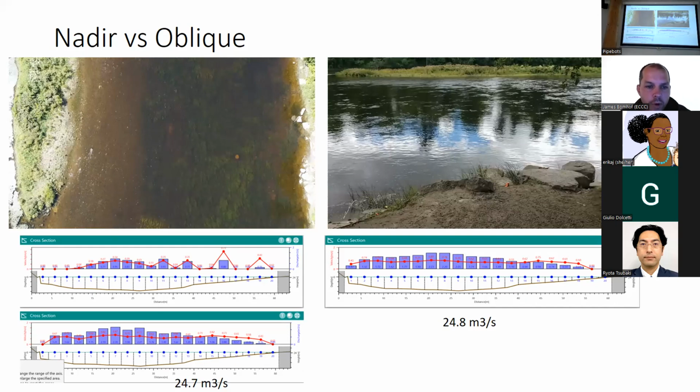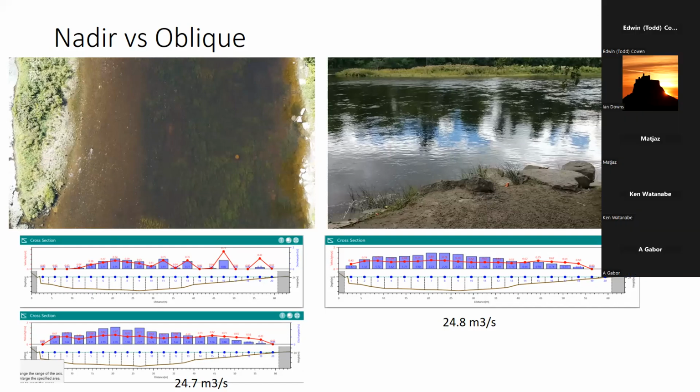Yeah, so for both these values, we didn't actually have an ADCP measurement at this site. So both these values are just estimated, calculated from image velocimetry, and they're not comparing to an independent ADCP discharge. Basically, the alpha value is 0.7 here, and I calculated that just by comparing it to the rated discharge, because the weeds obviously cause a lot of complications for that.